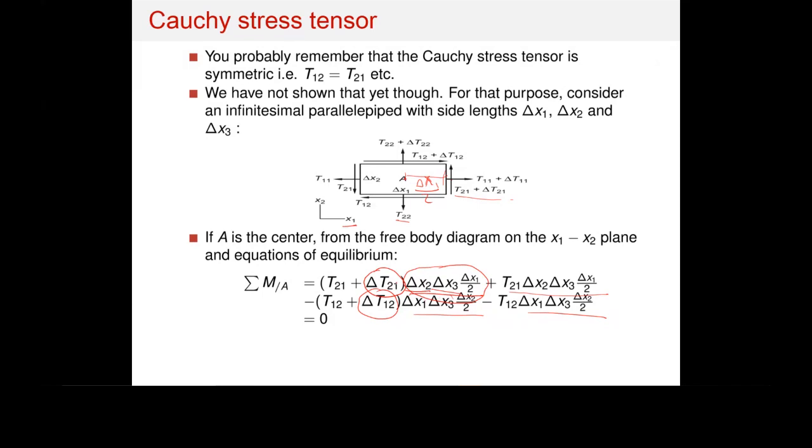It is possible to ignore them because these high order terms are simply not being taken into consideration. If you have large deformation, it is not going to be possible to make this sort of assumption. Or if the variation of the stress is too high, then this assumption again is not going to be valid.